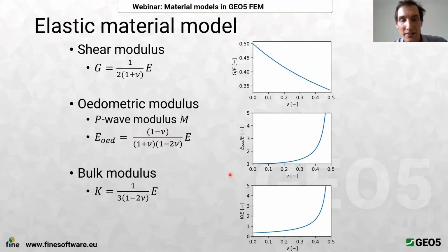So you typically know what the lateral stress would be, and you can run normal analysis, and if you are not satisfied with the lateral stress, you can prescribe it, but you have to do it reasonably, so you end up with some stress state that is admissible within the constitutive model that you will use in the second stage, because in the first stage you are not using any model, you just prescribe the stress. So I hope this answered the question.